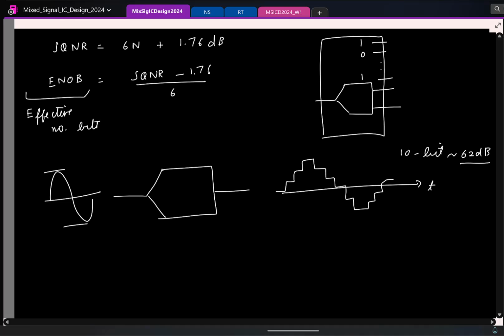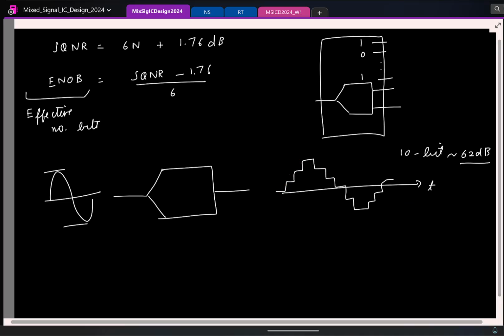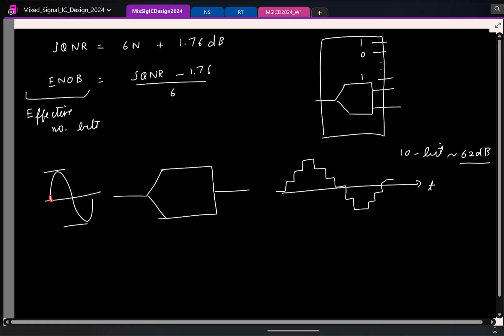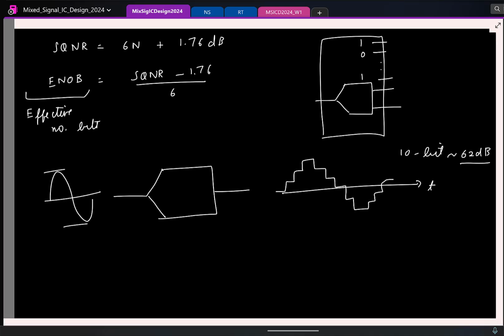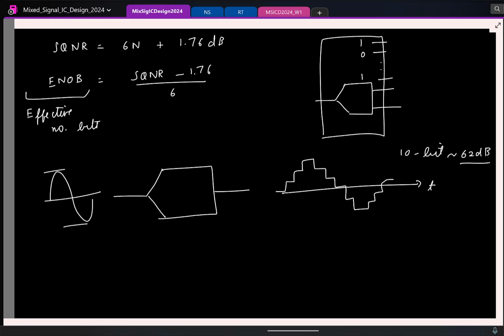And from the time domain, can you distinguish what is signal, what is noise? Exactly. I mean, you can say, oh, this looks like a sinusoid, but do you think it's possible for you to say my signal has this power, this noise has this power from the time domain? With respect to time, won't the noise be random so we can identify? No, that's okay, but if I give a sinusoid, it is going to quantize like this, right? This is what I'll get. Of course, if you subtract this and this exactly, you will find some random quantization noise. But the point is, you cannot exactly measure what is the noise from this alone, what is signal from this alone. Is that clear? So in time domain, you are not able to do it. So what do you do?